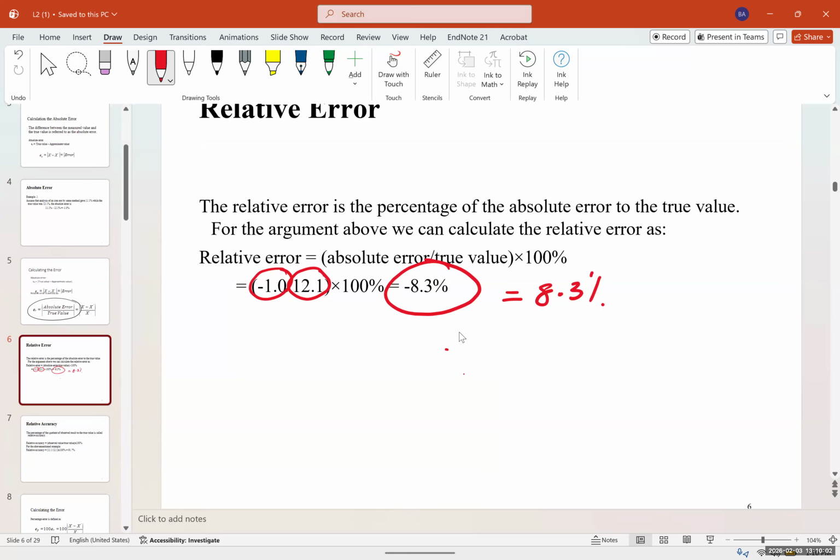So most of the time we show the error using the relative error. And for measurement tools like a DMM, digital multimeter, you would usually see this in the manual or the data sheets of the DMM, which shows the relative error. So for example, if it shows a relative error of 5% for measuring voltage, it means that you have a 5% error in the system. And that 5% is usually the maximum error that you get.